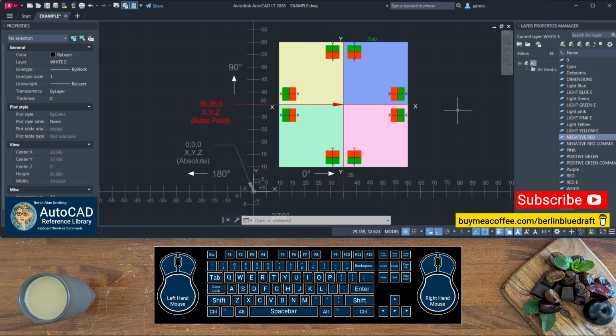This video tutorial demonstrates how to input X length and Y height values in separate fields using the tab key. This method allows for precise control over the dimensions of the rectangle or square as you draw it. A separate video will cover how to input these values using the comma. It is important to understand that the tab and comma keys operate differently when entering these values, so it's recommended to review both methods. For comma separation, refer to the next video.